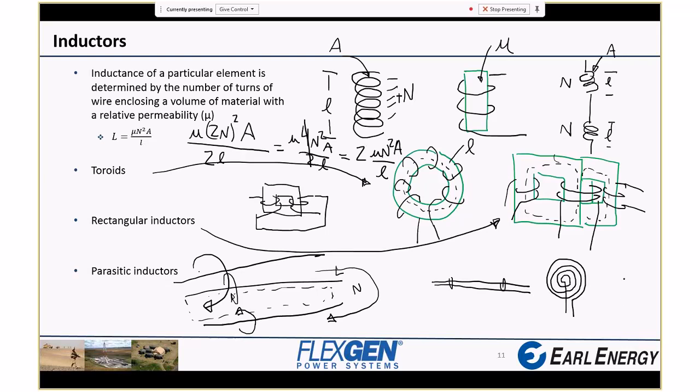There's the inductance of coaxial cables. Coaxial cables, if you cut them open lengthwise, have a wire in the middle. This is like TV cable. They have a wire going in the middle, and it's a bad way to show it. The return wire, I was showing like two discrete wires over here. For a coaxial cable, the signal comes down on the inside and it returns on the outside. So that's a different inductance.